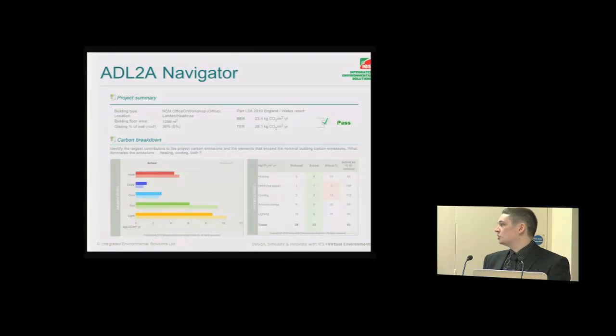I would want to perhaps look at improved controls, perhaps, if I've not already implemented photoelectric or occupancy sensing, see if I could introduce those into the design, or see if I can perhaps look at alternative technologies for luminaires. See if there's something more efficient that I could use to help drive that down.